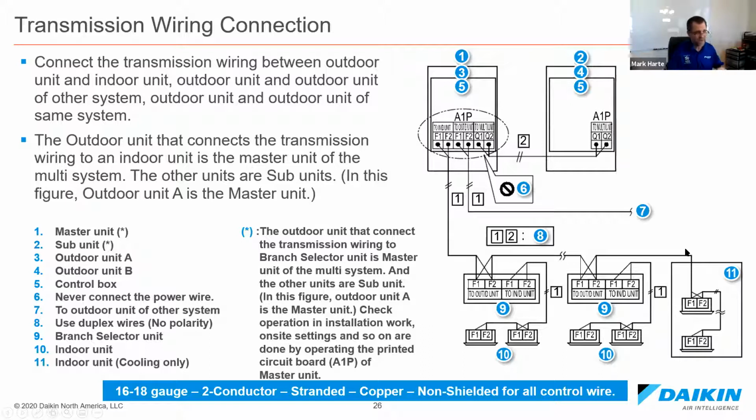Like I said, it's 2-wire. That's a 16 volt DC communication circuit. It sends data packets back and forth. Splices, wire nut connections, they are bad for that communication. So that's all we want. So it's a very simple low voltage wiring. We call that the D3 Net. D3 Net is our low voltage circuit.